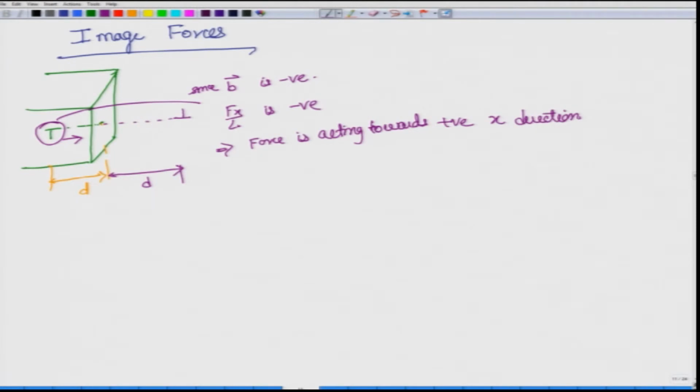Whatever it is, the total force acting onto this has been found to be related to as if there was an opposite sign dislocation some distance away from the surface, as it is inside the surface, and therefore, it is called image force. So, there is an image dislocation with a negative Burgers vector, because that is what is causing it to be an attractive force.